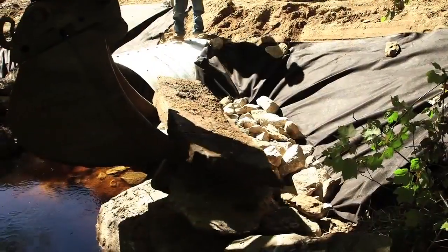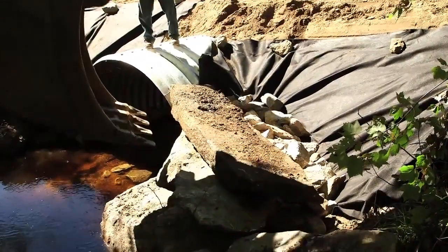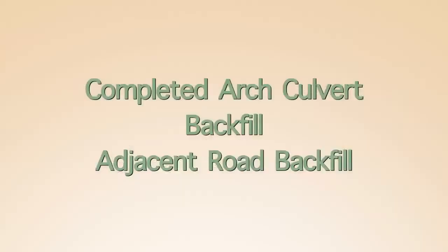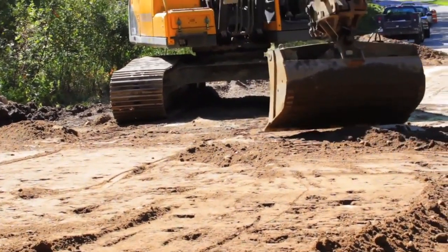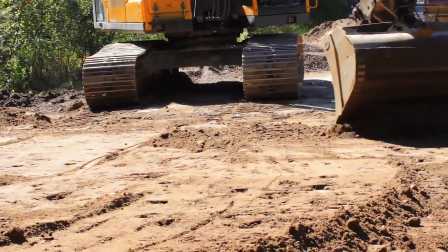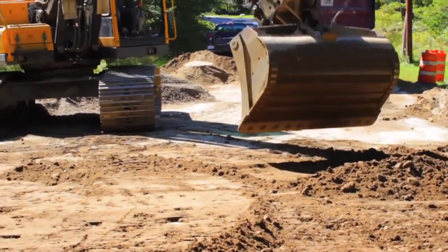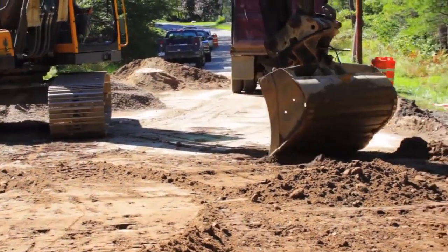Stone blocks from the old head walls, as well as new riprap, are used to stabilize the road embankment for the new arch culvert. Completed arch culvert backfill and adjacent road backfill. The backfill for the road beyond the designed arch culvert envelope backfill is typically just compacted with larger equipment such as an excavator or bulldozer.